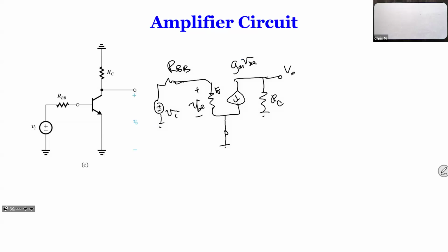Okay, so this is a very simple circuit. Because the emitter is grounded, basically this circuit is divided into two separate circuits, even though in the middle they have the common ground. So on the left hand, what do you have? Two resistors in series. What do you call that? It is a voltage divider.